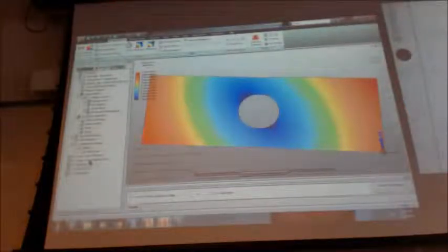It'll end up cockeyed a little bit. So you have to constrain it in the Z somehow. How would you constrain it in the Z? Well, you can maybe constrain the bottom, but if you do that, then you're not getting the deflection that you would normally get on the bottom for that part next to the hole.